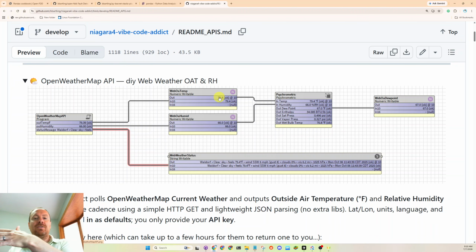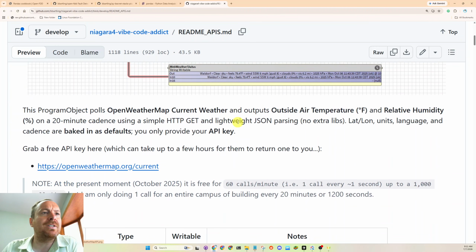could bring that air into the building, and more than likely, if it's in a dew point economizing mode, where the dew point is okay, we would be in mechanical cooling and economizing at the same time, because the return air coming from the building would have more humidity. So basically this enhanced dew point logic, you can squeak out a little bit. It's less load on the chiller, basically. Hopefully that makes sense.